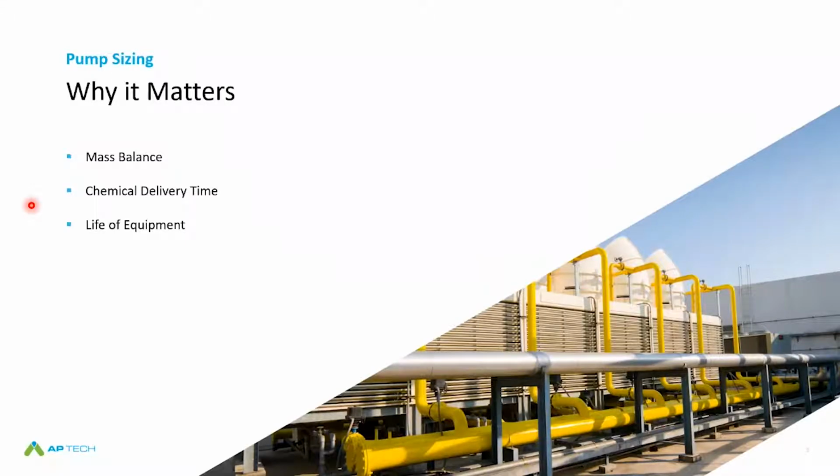So why it matters. Pump sizing is very important when it comes to mass balance. Mass balance is, I think, the principle of water treatment, and basically what mass balance is talking about is the requirement of product or chemistry needed for that particular application. As water treaters, we're typically used to parts per million, understanding that 120 parts per million is 1 pound per 1,000 gallons of water.